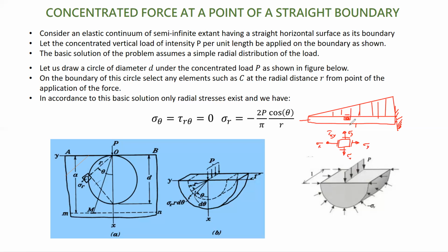Do I have shear here on the top? No. So the shear stress tau xy, if the thickness of the beam, I believe, was 2c, and the axis was at the middle, the central axis of the cross-section of the beam. So at y equal to plus c and y equal to minus c, where y positive in your textbook is shown at the bottom and this side is x, I don't see any shear stress here and there.